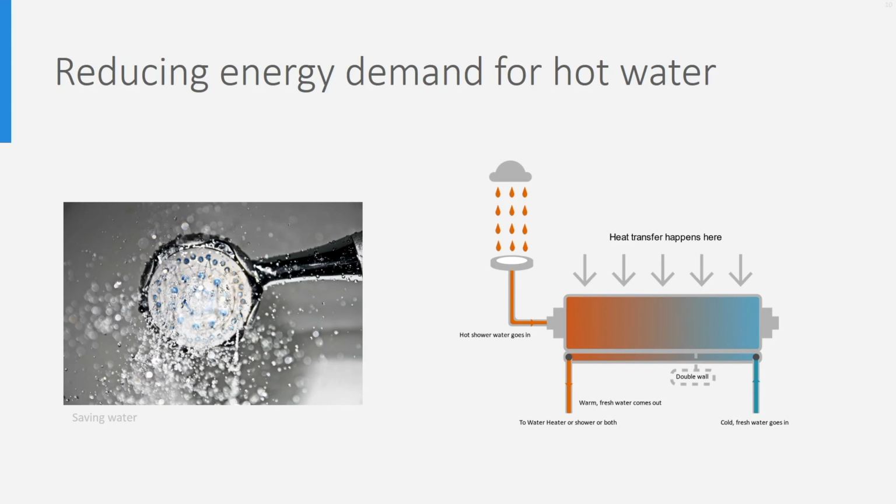For warm water applications, you only need around 45 degrees Celsius, so you might suggest not heating the tap water higher than 45 degrees Celsius. However, to prevent Legionella bacteria growth, which causes diseases, you need to heat at least to 60 to 65 degrees Celsius. Heating the water to 65 degrees Celsius once a week should be enough, but most systems apply this temperature continuously. Sometimes also chemicals are used to kill the bacteria in the water.